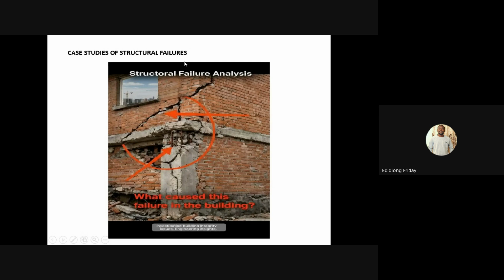Then extend your columns to the final floor, because this is a corner location and it's important that a column should be there. Then, with proper workmanship, the areas that have visibly failed will be chiseled and then reconstructed. That's my take on this.